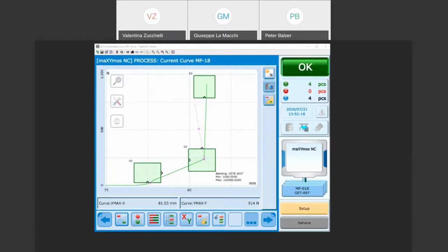It's more or less the same curve, but with additional calc elements. This is also an example which I used a lot of times on site during a commissioning, for example, if you want to calculate your real press position. Also, if you need to cover some big tolerances, with this calc element I'm just calculating the point where we have reached the block position and the point where we have touched the part. And the distance in between those two points is 3.23 millimeter.